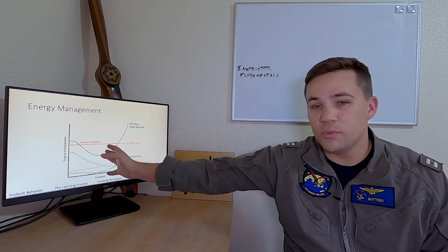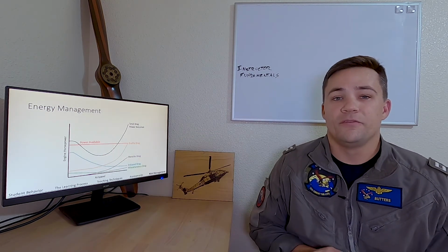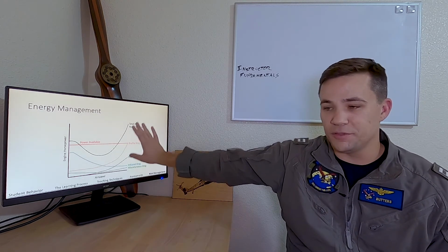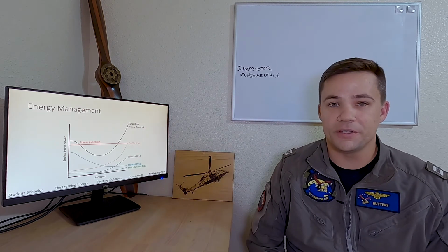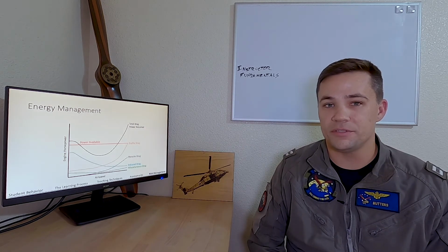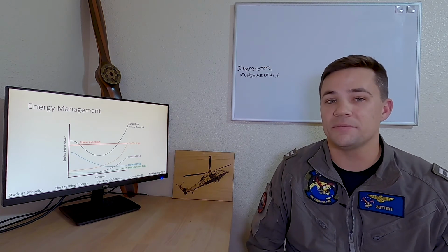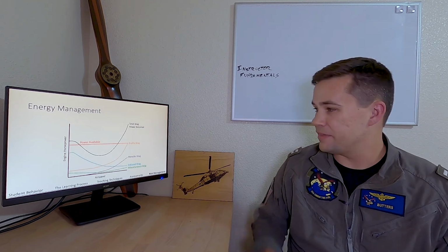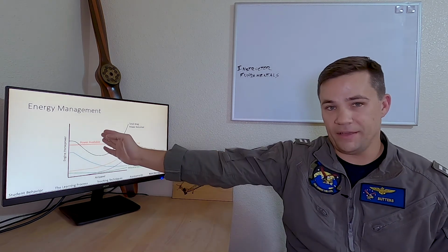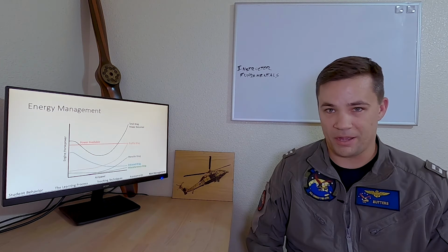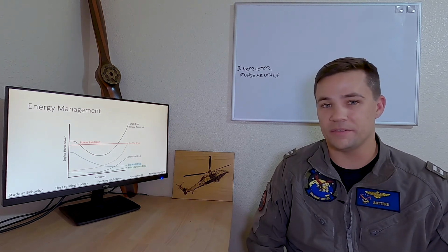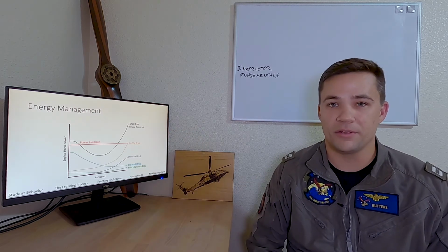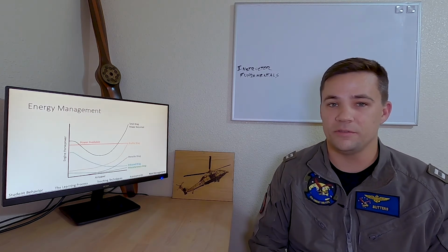So this is where you want to be, again, forming that defensive posture as an instructor. On the right side of the curve, be more relaxed, not really guarding the controls very closely, maybe allowing the student to make some more mistakes, to try some things out, to see the consequences of ideas that they have. Start getting into that left side of the airspeed curve, that power required curve, and now your spidey senses need to come up. You need to start realizing your margins are smaller. The amount of power that you have to correct a student's mistake is smaller.